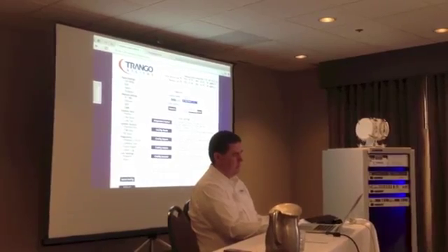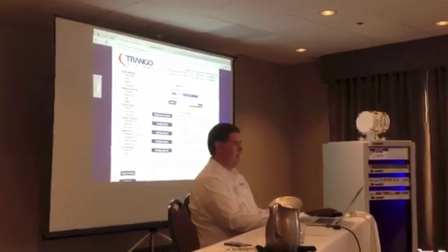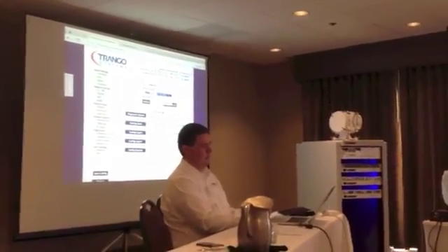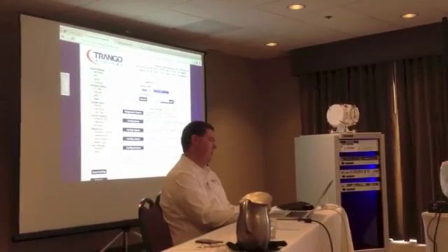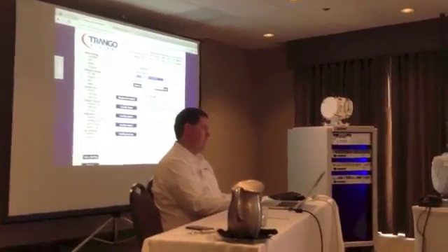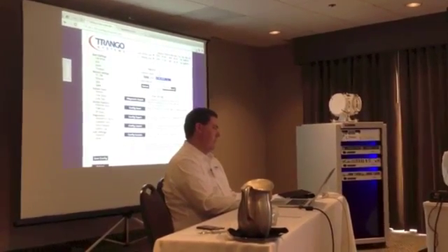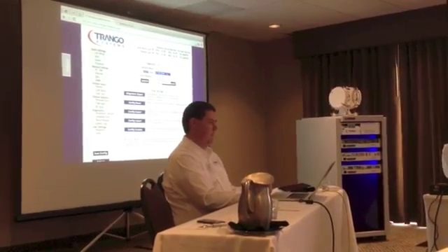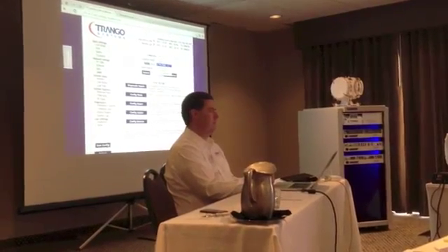If you have the status logging turned on, every 30 seconds it logs what the link is doing. Yes, the RSSI is here. Yes, I have a lock. This is the MFC. This is my temperature. I'm putting in 98 megabits and I'm getting out 96 megabits or whatever, every 30 seconds. Nothing useful will be in your log other than the status every 30 seconds. If you have the status logging on, you'll only get 12 hours of history. So, something happened 13 hours ago and you wanted to see what happened? Guess what? You're too late.